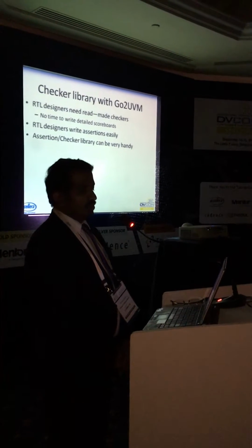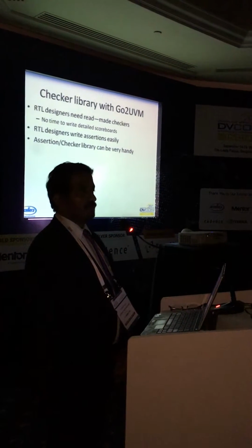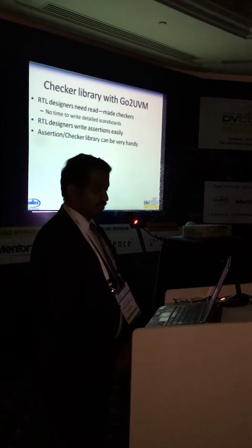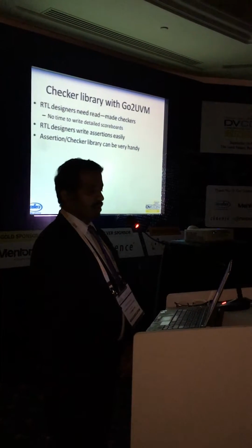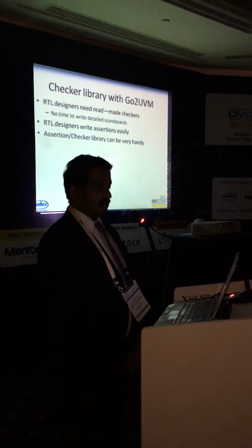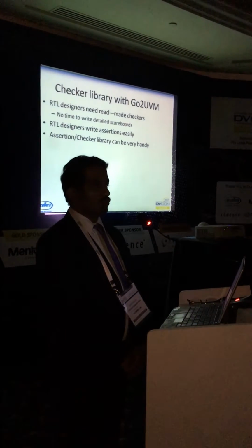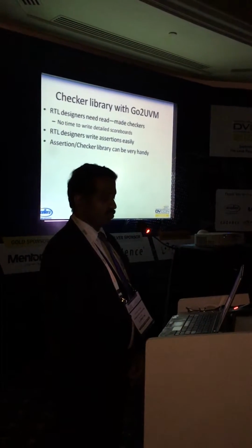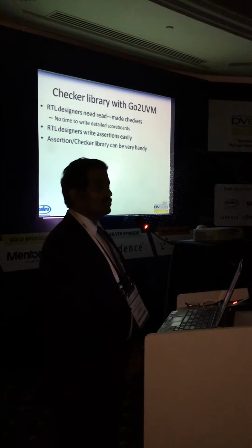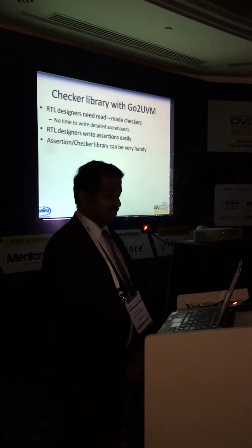It's a new construct. Don't worry too much about that. It's just, let's say, an encapsulation for all your assertions. However, RTL designers need ready-made checkers. They do not have the time to write a lot of assertions or detailed scoreboards. Right? Detailed scoreboards are way too far for an RTL engineer.